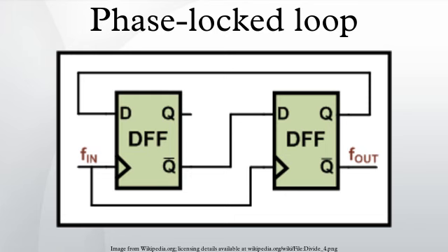Block diagram. A phase detector compares two input signals and produces an error signal which is proportional to their phase difference. The error signal is then low-pass filtered and used to drive a VCO which creates an output phase. The output is fed through an optional divider back to the input of the system, producing a negative feedback loop. If the output phase drifts, the error signal will increase, driving the VCO phase in the opposite direction so as to reduce the error. Thus the output phase is locked to the phase at the other input. This input is called the reference.